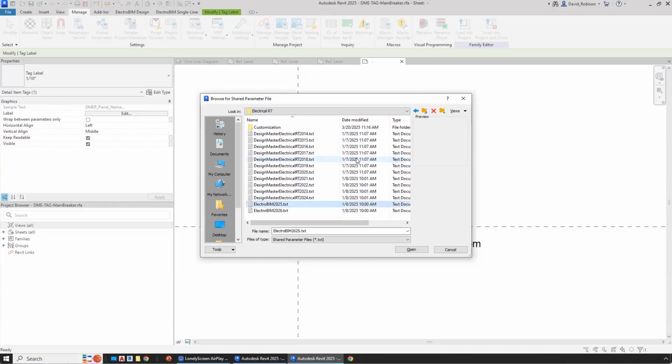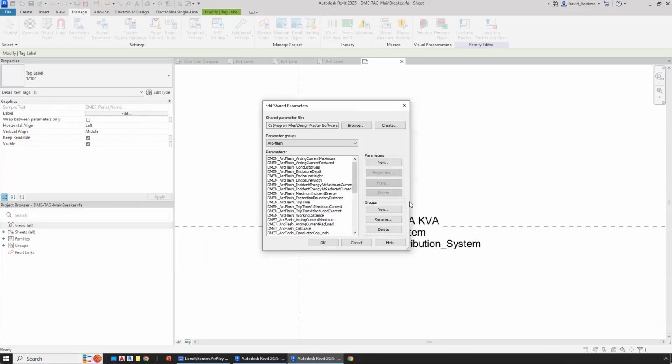There are slight changes as the versions of Revit change, so choose the oldest one that you're using, typically. Then this will pull in our shared parameters while you're making changes. If you are using your own, then you can come back here and change it back when you are done. It doesn't really matter to Revit. Revit doesn't care if you're changing it back and forth.